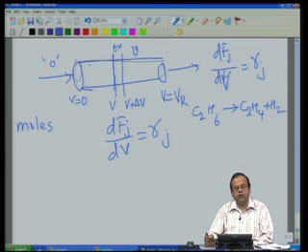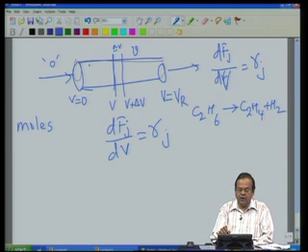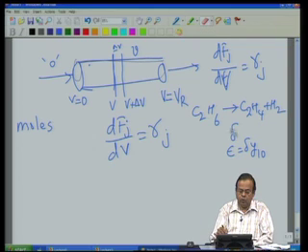We had earlier spent some time on how we calculate the flow rates and so on, or how they are dependent on temperature and pressure, but let us reiterate this example once again and how it affects the design equation for a plug flow reactor. Now, what is happening here is 1 mole is giving rise to 2 moles. So, without going into details, we have delta, the change in number of moles, then epsilon as delta times y_A0, that is initial moles, all these things we had considered earlier. So, I am not going to repeat once again, but the idea is the following.